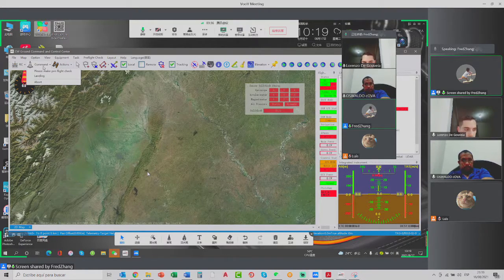And abort, you know, this morning I showed you the video for the craft takeoff and the landing. Right? When the craft is using the VTOL multi-rotor to climb or land, you can use the abort. It means the abort can only be used when the drone is working in multi-rotor mode. Okay. It can only be used once.